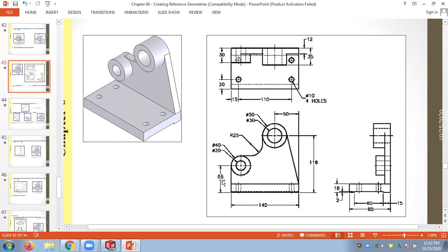Now when you start with the front view, you don't need to draw these holes. These are separately drilled by the cut tools. So I don't need to draw these two holes. And I don't need to draw this cut here also, that is later. We can handle that later. So these dotted lines are for this cut. When you look from the front view, you can't see this cut. That's why you have a small dotted line here.